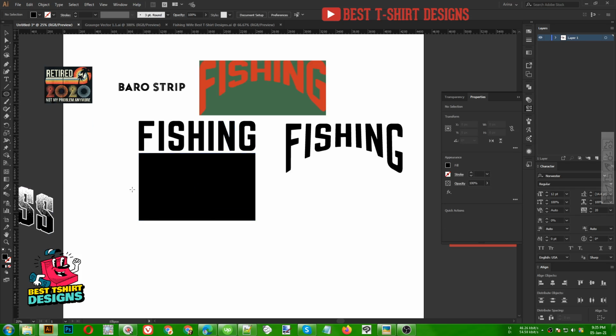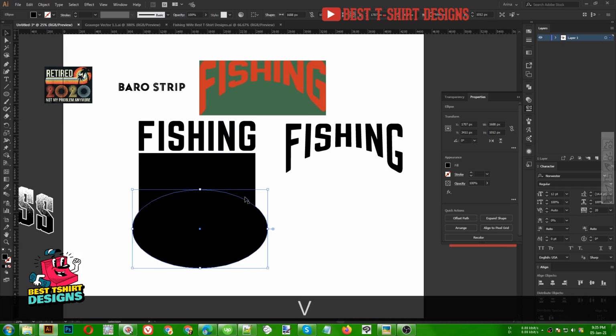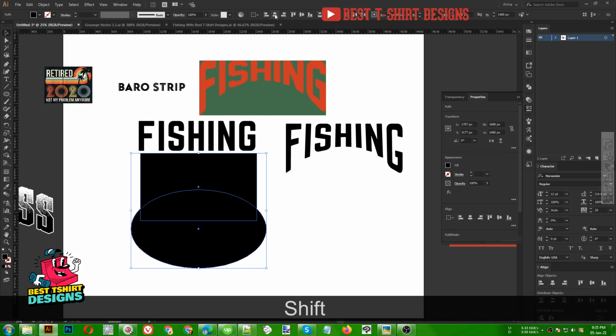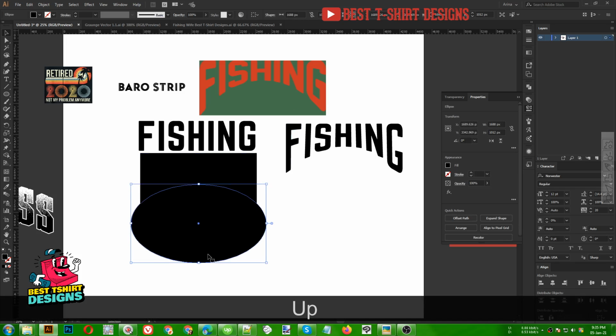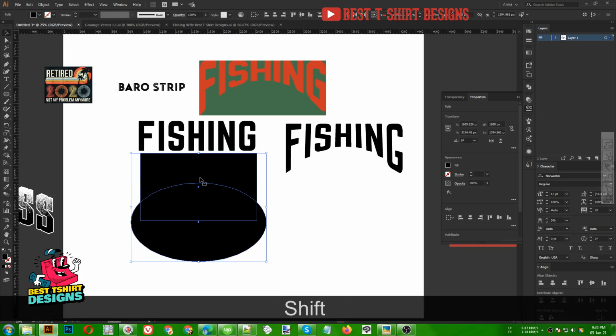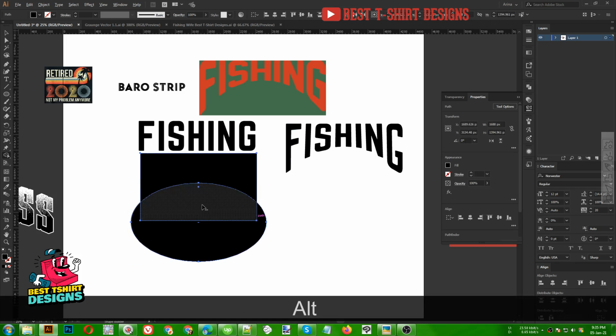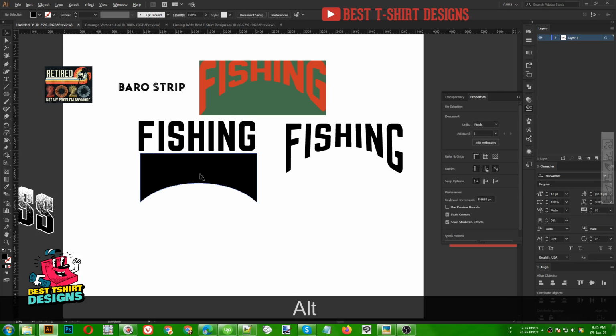So with that ellipse I'm going to create an ellipse like this, maybe this, then selecting these two, then aligning them in the center position, that is good. A bit something like this, that's good. Let's select these two, this rectangle and my ellipse, press Shift M for Shape Builder. Now I'm pressing Alt and then erasing this part because I don't need that.